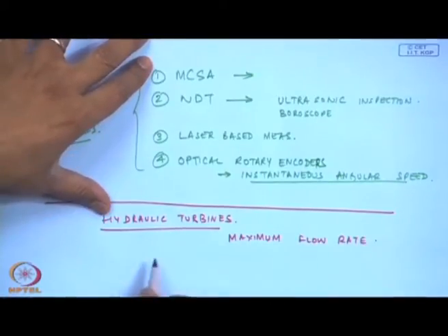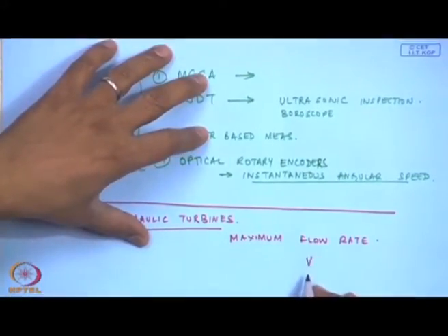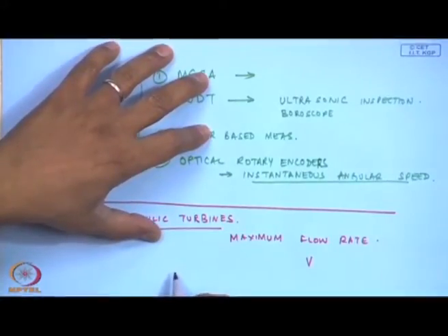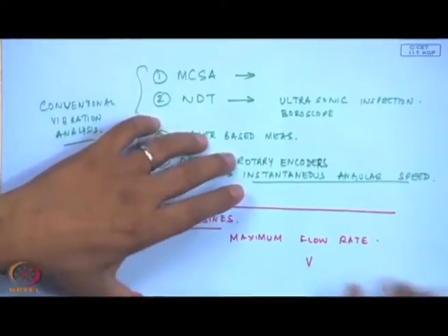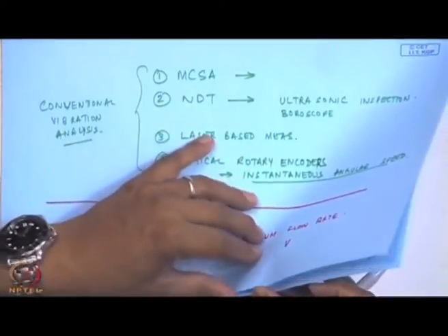Okay. Because if the flow rate increases and the velocities become so high, because to conserve energy, the pressure of the liquid falls below the vapor pressure, so what is going to happen is vapors will be formed or bubbles will be formed in the pipeline.